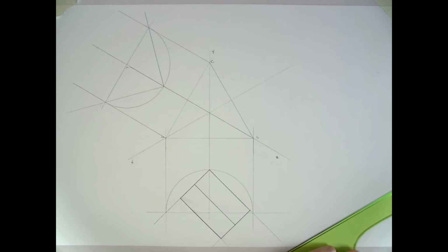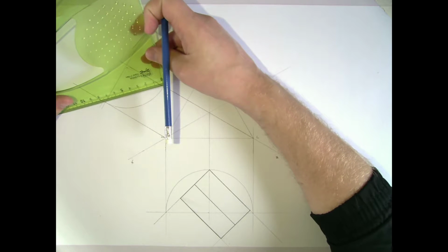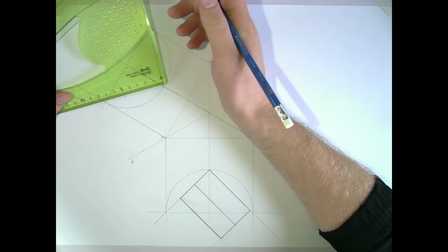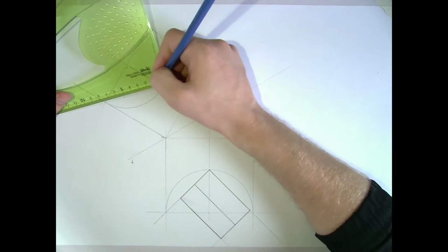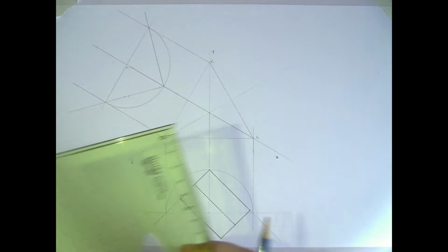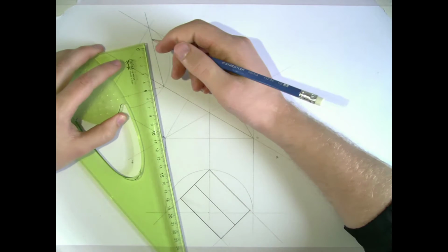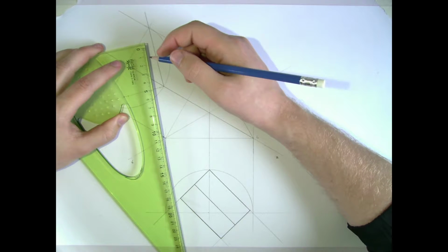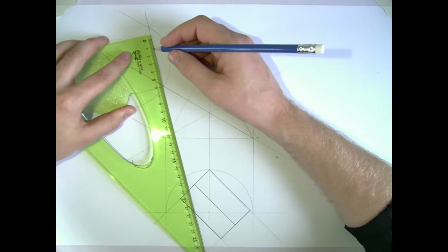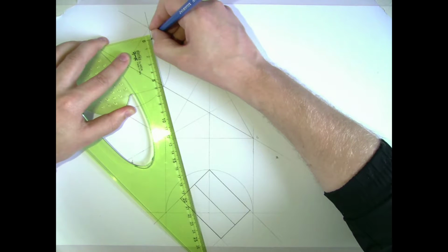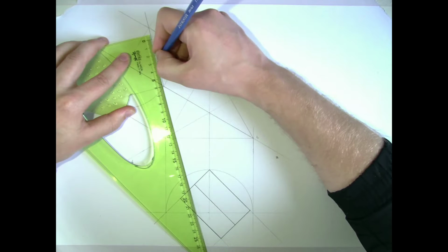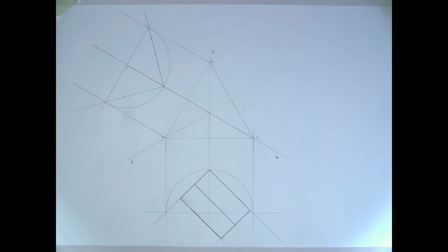So with those axes set up, what we can do now is draw the end view, or the elevation. We are given a width across the front here of 50. We're also told that there's 40 millimeters, so if 40 is the space, it'll be 5 on either side. So I'm going to mark them. And then we have a number of heights that we're marking up along this also. There's a 60, which is the very top height, 40, and 30.